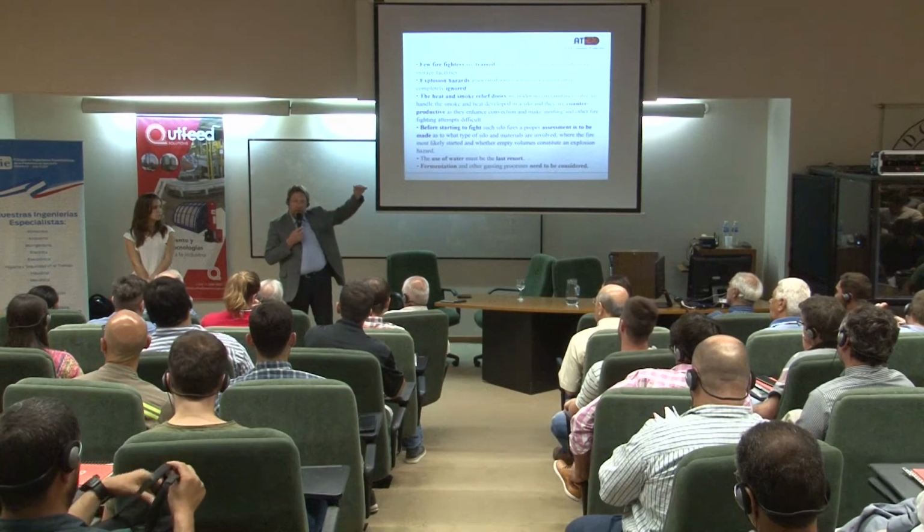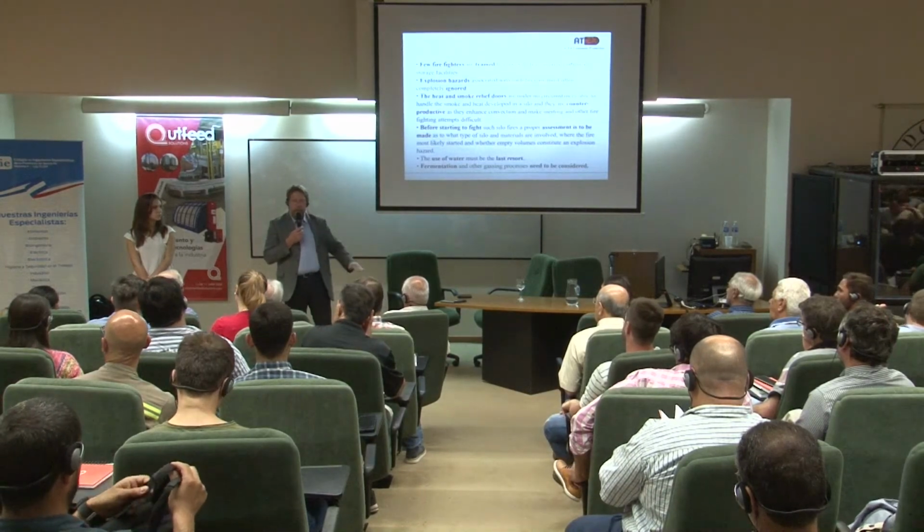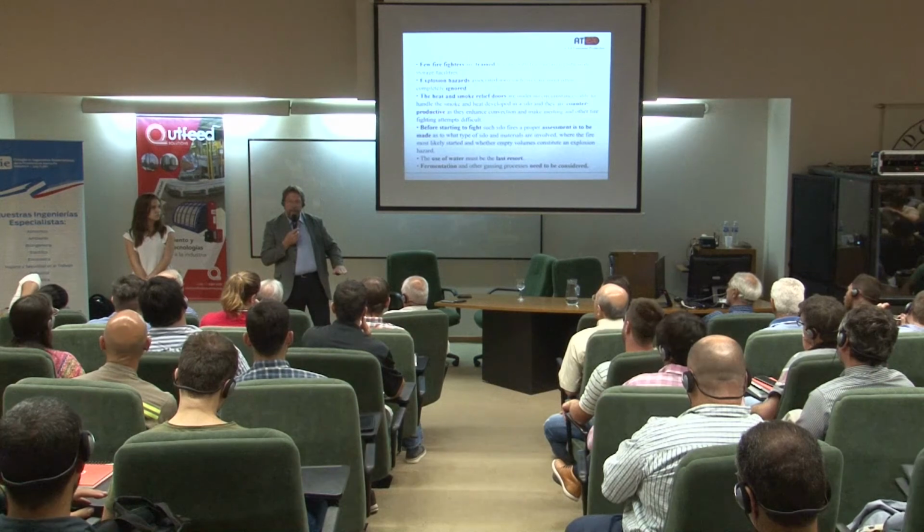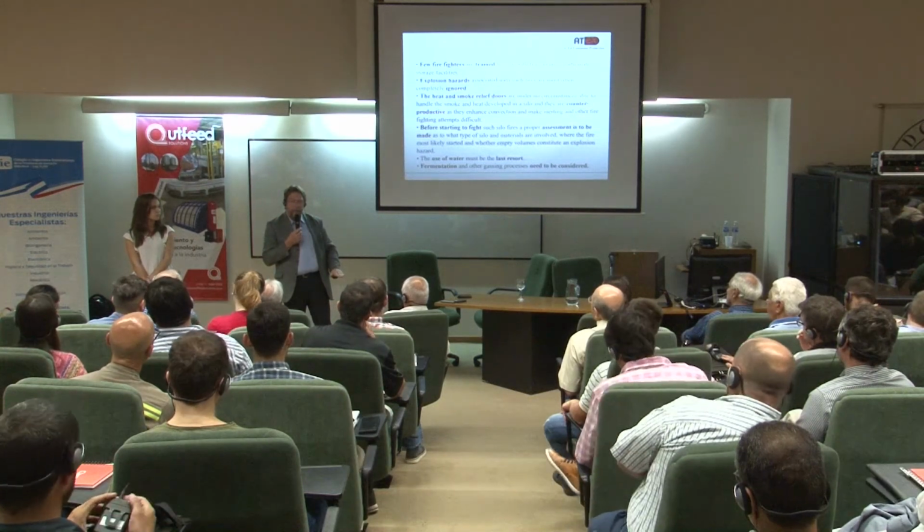And you remember what I presented, the pressures that we got in the silo. If we ignite on the top and the flame just burns down, it was very small pressures. If we ignite on the bottom, very high pressures, because the flame can kick off and accelerate into the volume. But if you have somewhere in the bottom small openings, then this kickoff doesn't happen so fast.